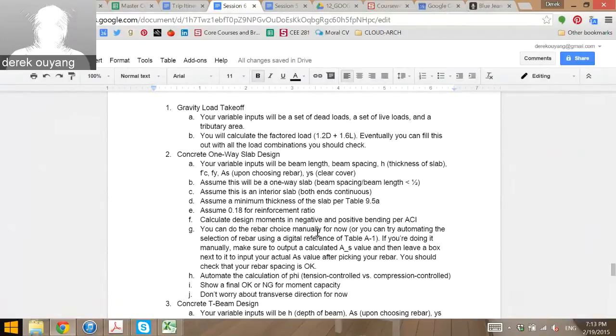draw what it would look like. You would have on one end, in either logarithmic scale or whatever, the moment you want to design for. And then over here you have another one on a completely different scale. It might not even be matching here, but then you've got, say, B, and then you've got D here, and then a thing that says pivot, and then you've got your reinforcement ratio here. And basically you would plot this point and that point, and then you draw a line there, and that becomes your pivot point, and then given a B, that tells you your rho. That just seems super archaic, but that's exactly what a spreadsheet will do for you, right? And that's the whole concept of us automating work for ourselves, because this is just streamlining all those formulas back in the day when they didn't have spreadsheets.